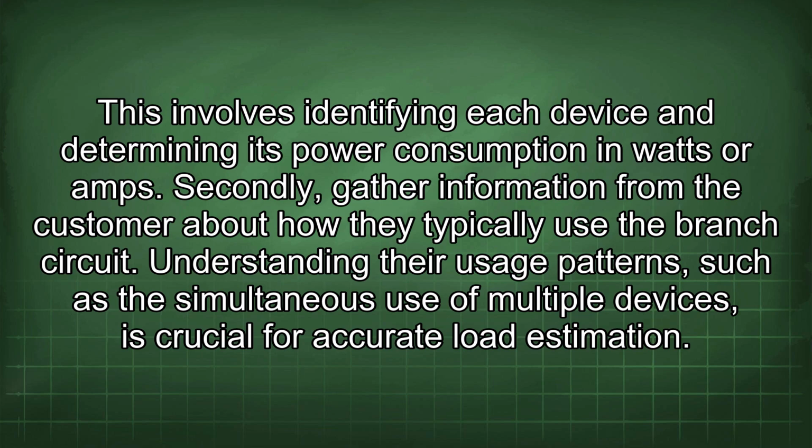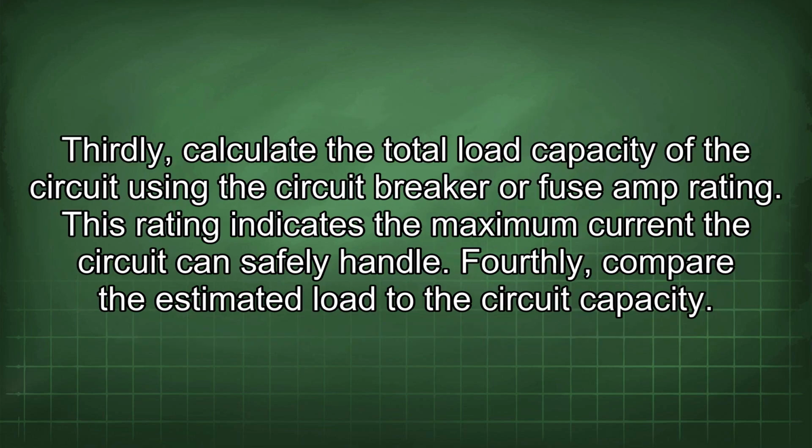Secondly, gather information from the customer about how they typically use the branch circuit. Understanding their usage patterns, such as the simultaneous use of multiple devices, is crucial for accurate load estimation. Thirdly, calculate the total load capacity of the circuit using the circuit breaker or fuse amp rating. This rating indicates the maximum current the circuit can safely handle.